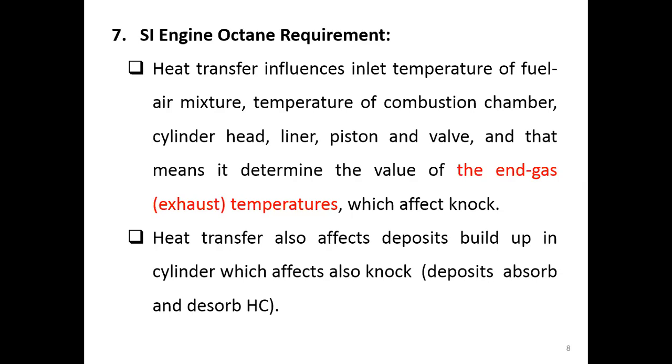Okay, the heat transfer also affects the deposits, something that is left over. It won't go out with the exhaust, it is just left inside your cylinder, and it starts to build up. And this deposit can absorb heat and transfer heat depending on the stroke of your engine, because we have temperature variation.